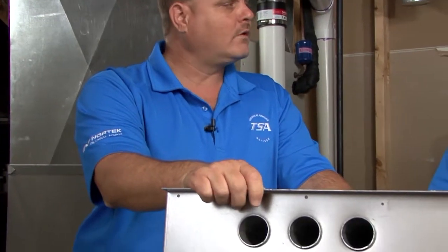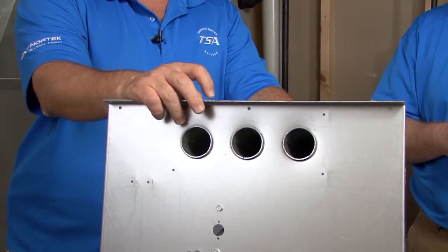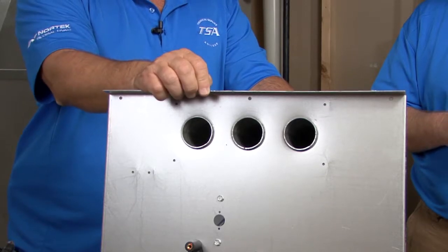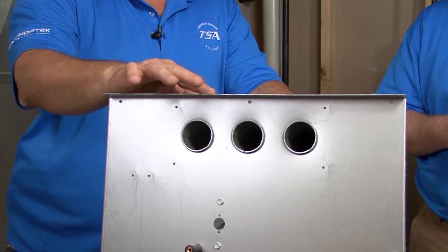We have had it in the past where this is the top of your heat exchanger, and that's got a seal to the cabinet. And we've had where contractors would utilize an uncased coil, and they'd shoot a sheet metal screw through the cabinet of the furnace down through and hit this. This is a pretty thick metal, and it wouldn't pierce it. So it'd literally lift up the cabinet. Now you got a gap here.